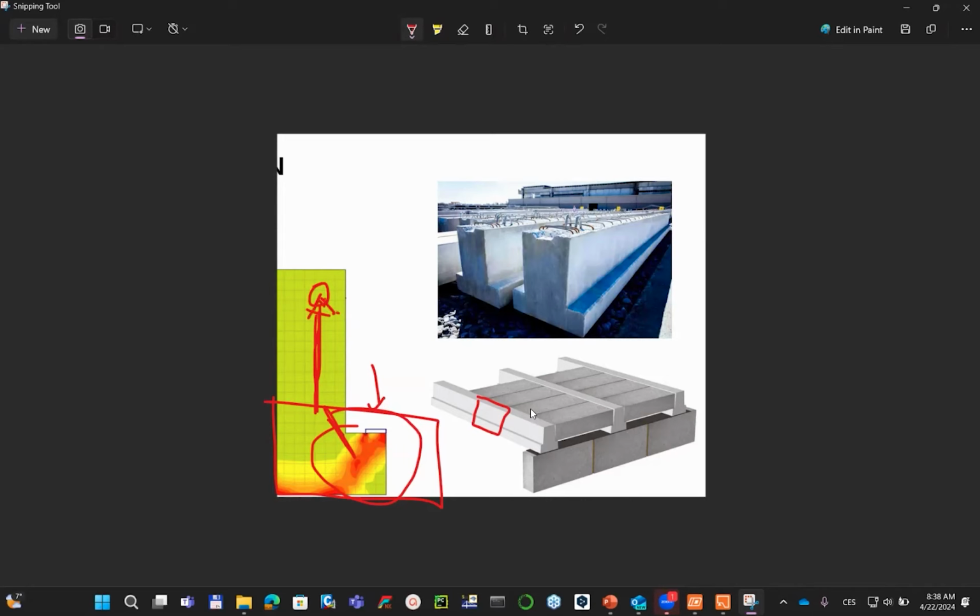Otherwise, maybe you have another experience where to put the supports, or how to handle a structure like this, but generally this model is also supported by our committee. There are examples for design and code check of structures like this, and how the stress is redistributed to the reinforcement rebars and to the concrete. So based on these assumptions, we used the support at this location.